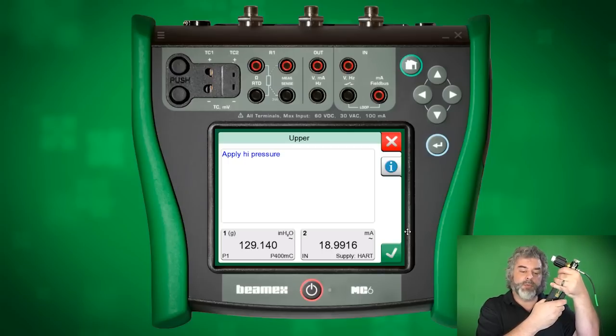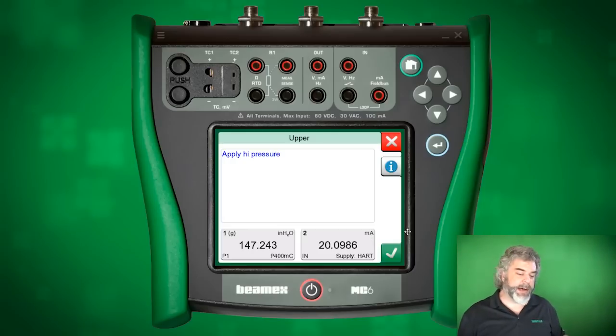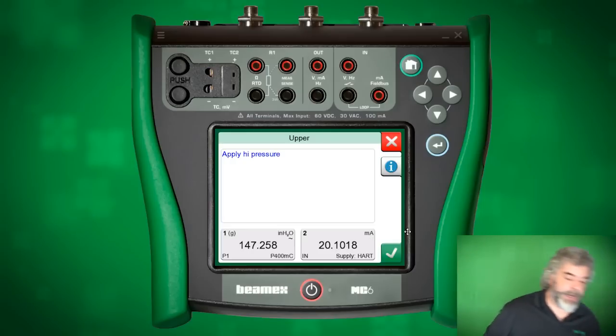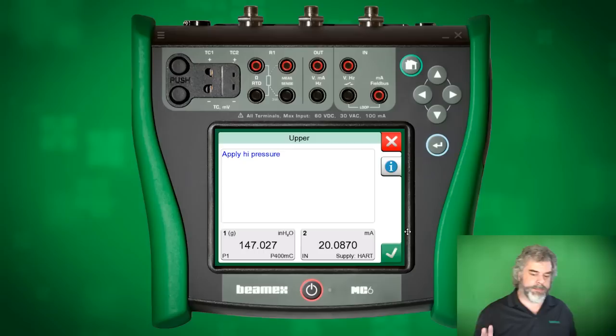And I'm just doing a small inches of water transmitter, but if you're gentle, you can use a pump that's too large for what you're doing. Now, I'm at 145, and I overshot it a little bit. But I'm going to let it stabilize. With pressure, you should let it stabilize. Even the temperature on the pressure hose can change your pressure. Now, I would give this maybe a couple minutes, but for the sake of time, I'm not going to.